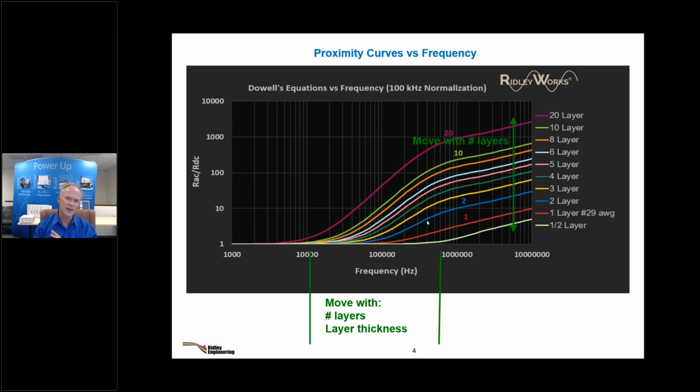If you go to a critical conduction mode converter, then you really have to start thinking about using a different topology for the PFC inductor. I would use a gapped ferrite for that. I would go back to that because there's going to be a lot of core loss on that one. But hey, we can do the analysis of it. We can extract the curve, and then you could design that inductor in RidleyWorks as though it were for a buck. Lay out the windings, spit out the model, and then go load it into your PFC simulation. That's the beauty of these models.